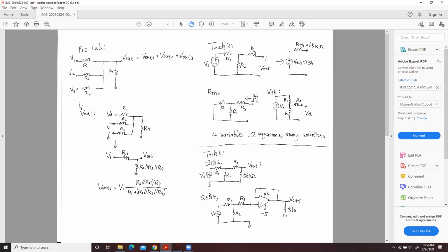And how you analyze the circuit is something like this. Okay, when you measure the resistance, the current goes through this way. Okay, go this way. And since this is a voltage source, you can put it as a short circuit. Okay, a voltage source looks like a short circuit. If this is a current source, that's an open circuit.